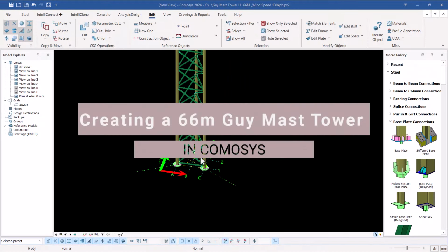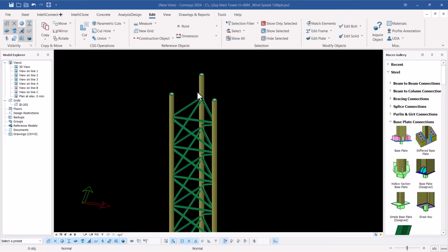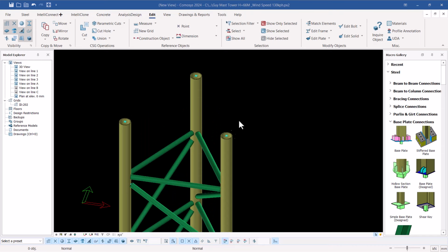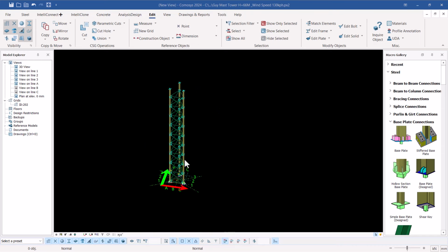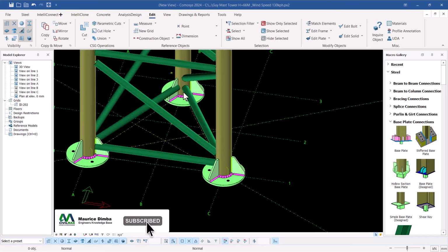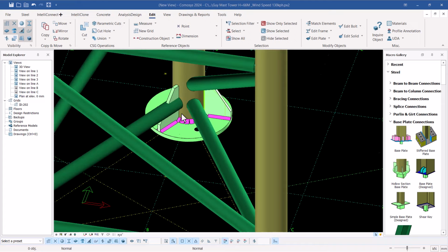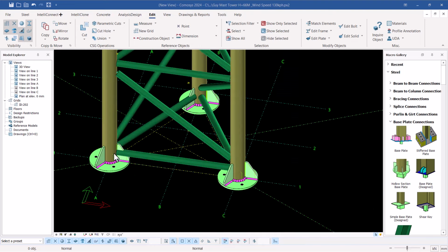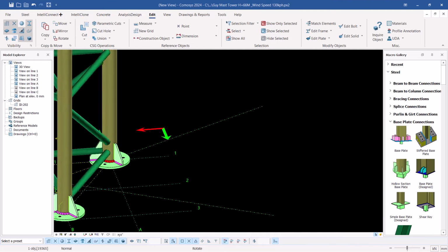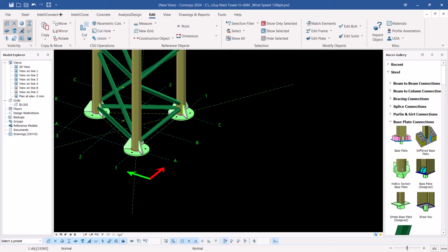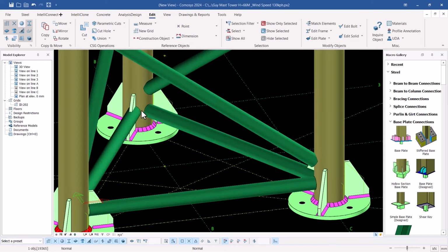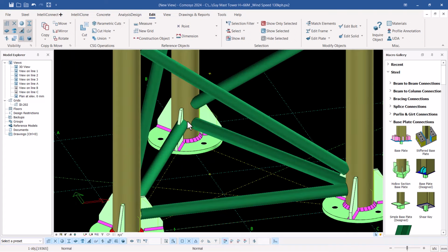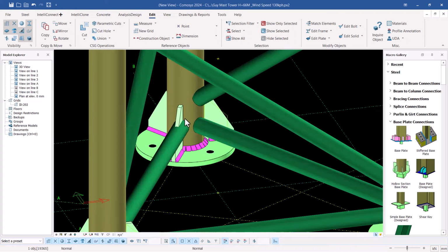Welcome back. And now we want to populate this segment all the way to 62 beta. So prior to that, we want to create a flange on top here so that it will mesh with the bottom flange here. But if you take a look here, there's a little bit of clash. So we want to rotate this to avoid this clash. The same thing applies here also. You can see it applies only here, but to avoid a duplication of this particular clash, we have to rectify this.